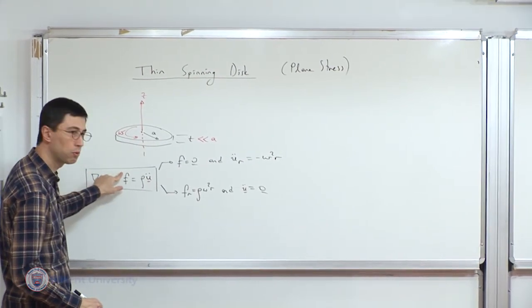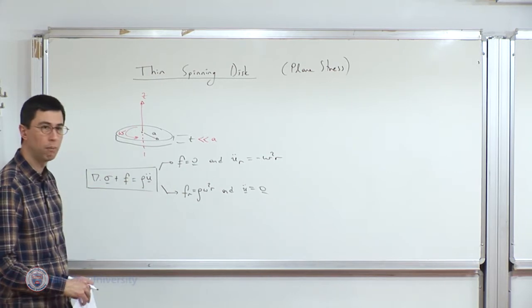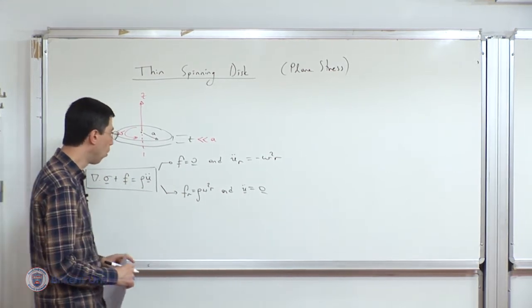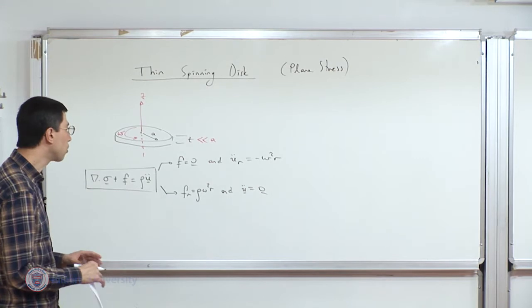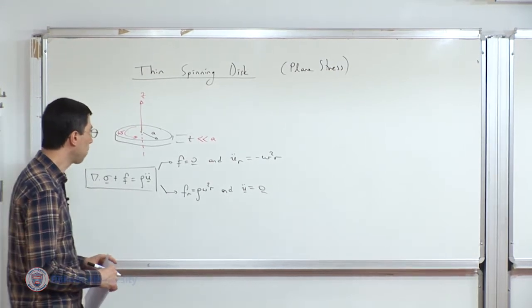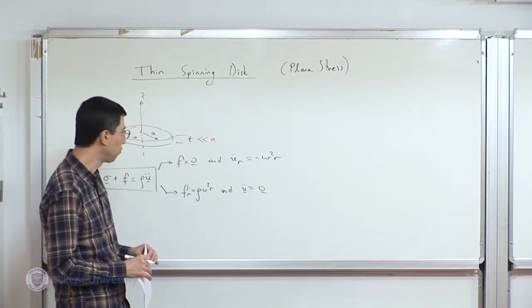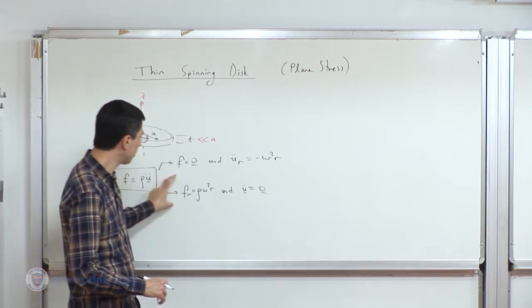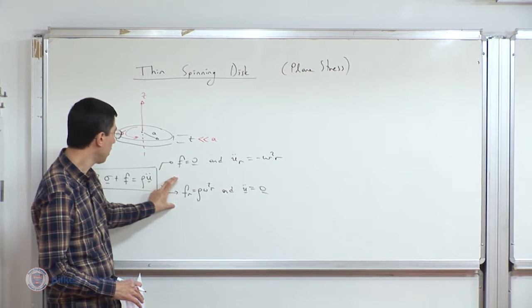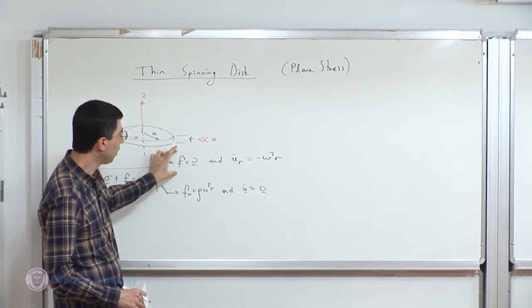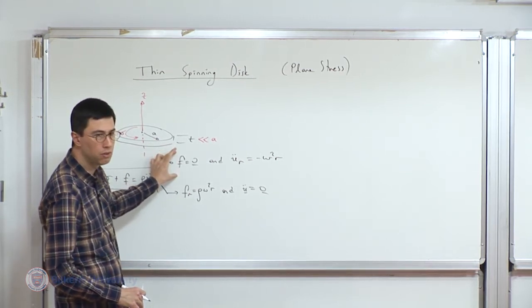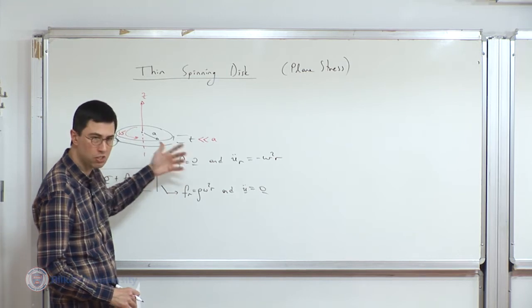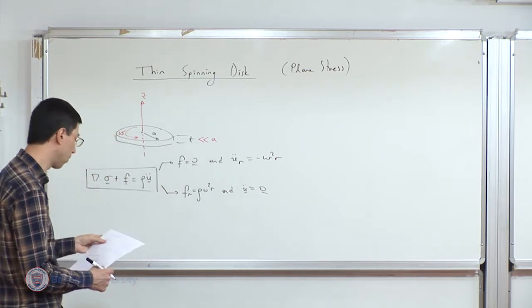Instead, I put that term on the left-hand side, and I've said that the radial component of the volume force is rho omega squared r. So these are two different ways to look at the same problem. For instance, I'm going to show you some numerical problems. In that numerical setup, I have actually used this setup because it's easier for me. But when I do the analysis, I'm going to use this approach. Really, it doesn't matter. They are essentially two equivalent views of the same thing.